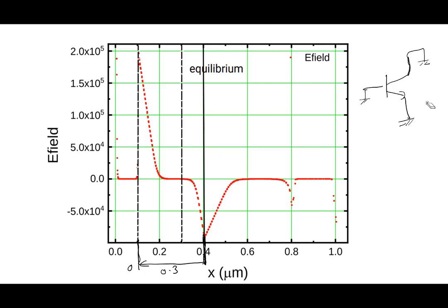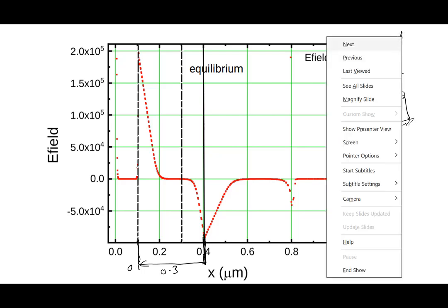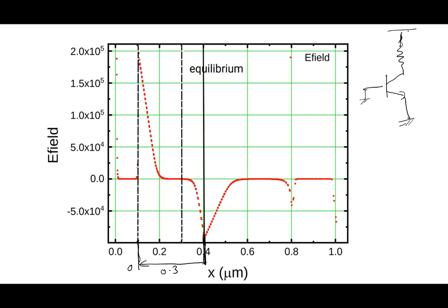But now in many devices, for example, if you're making an inverter or amplifier, it can happen, let's say in a simple inverter, that when you apply 0 and you apply, let's say, 5 volt or 2 volt or whatever, the voltage here will turn out to be 5. Because you have not applied anything to the base, the emitter is ground, so the transistor is still off, but the voltage at the collector is 5 volt. So from the point of view of the base width, this is the worst case situation, because you have not applied anything here.